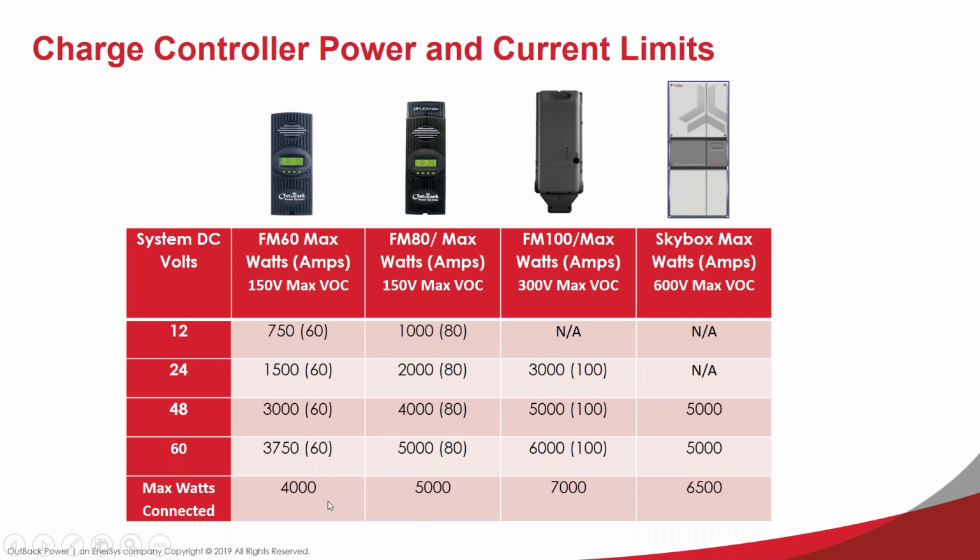Okay. So the maximum connected watts is what you can safely connect. A lot of people like to oversize their arrays for winter time or shading issues or whatever. So this is the maximum connected watts that you can have with each of the four MPPT devices.